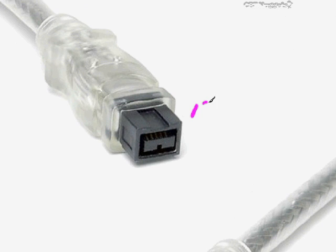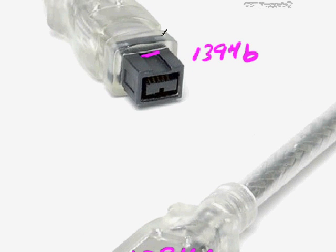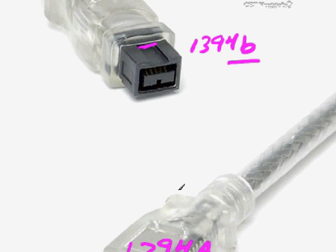This is a 1394B cable. And what we see with this one is it's known as a bilingual cable. It uses 9 total connectors on the top. I don't know if you can see them, kind of small there. But there's 5 connectors on the top, and underneath that you would be able to see 4 additional ones. And it has a narrow notch up here at the top. The narrow notch designates this as bilingual, which means you can connect this to the device you're trying to work with, and the other end, for example, into your PC, and you can work with a 1394B device connected to a 1394A port, and that should work just fine.